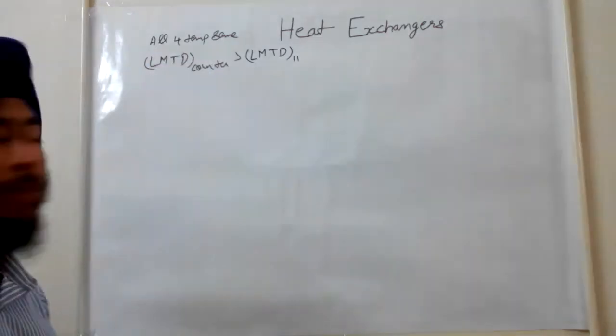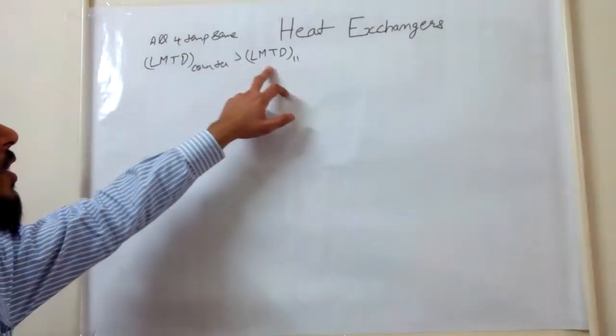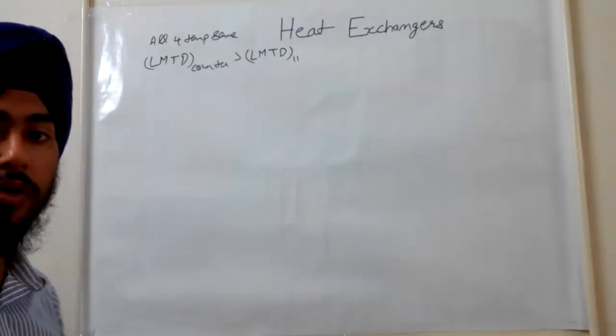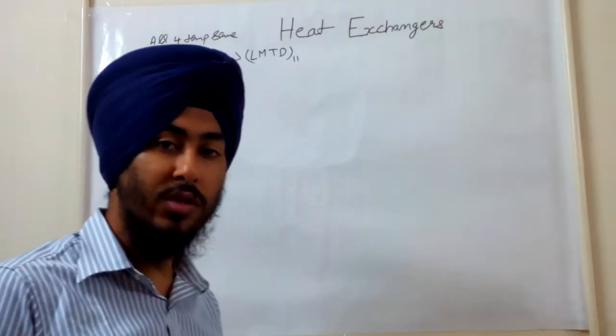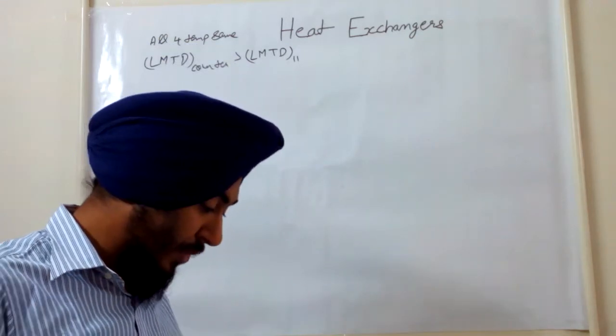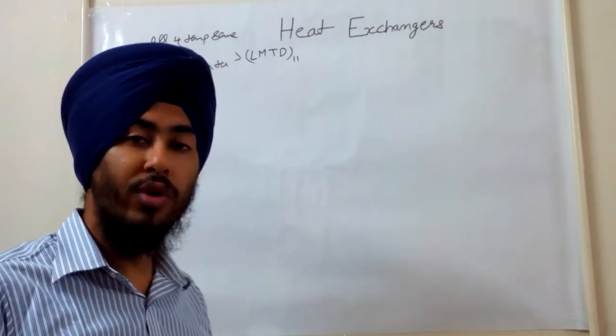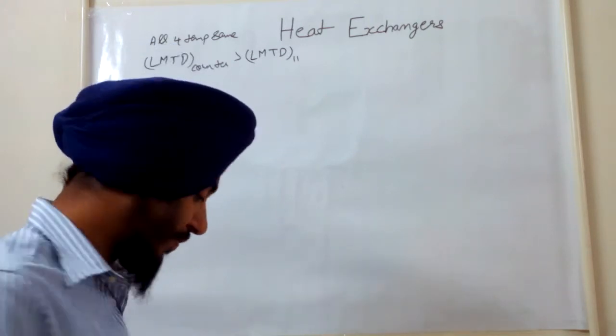All four temperatures are same. LMTD of counter will always be greater than LMTD of parallel. Please note it. It is an important point. Now let us solve some question. It is GATE 2008 question.